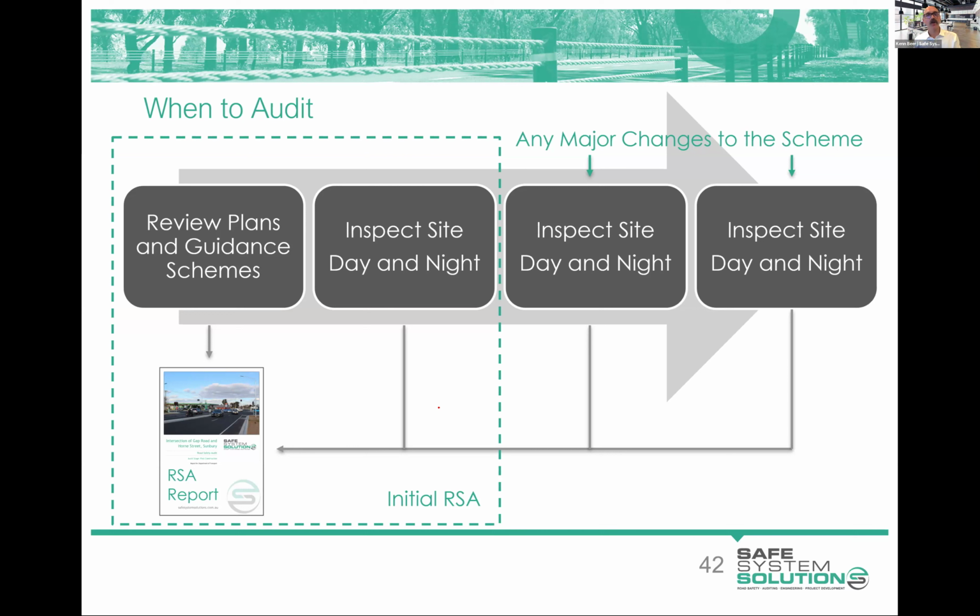If somebody decided to avoid this area because they could see queuing cars, which streets are they going to go down, and where do they go? What's the land use around there? If people wanted to make U-turns, are they going to be able to do that safely? If people are coming along here at speed, are they going to see the end of a queue? So you're getting that general understanding of how it's all going to play out.